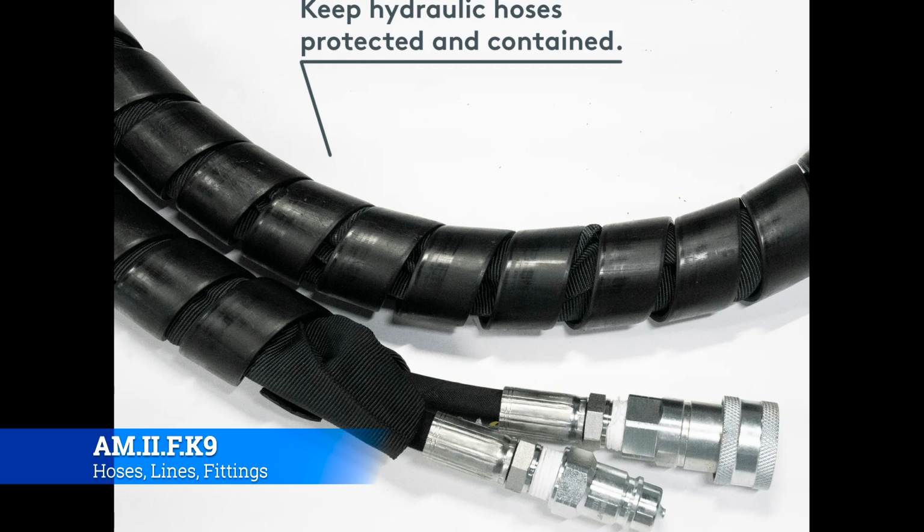In the OH-58 it operates under about 6,000 psi if I remember right, and it only has a quart of fluid. So the moment you get any sort of leak, it basically blows all the fluid out, and then you're without hydraulics, and that's what happened in this flight.